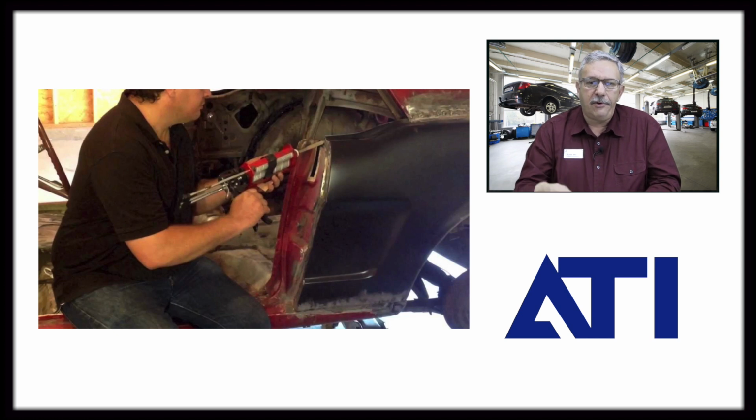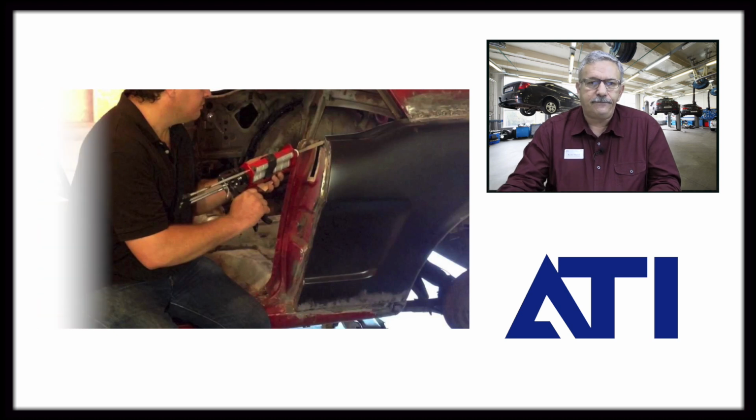Make sure that as you're writing the estimate or the repair plan, you are going in and researching for that specific vehicle by VIN and by model production date. Make sure that you're getting the information that's correct for that vehicle.